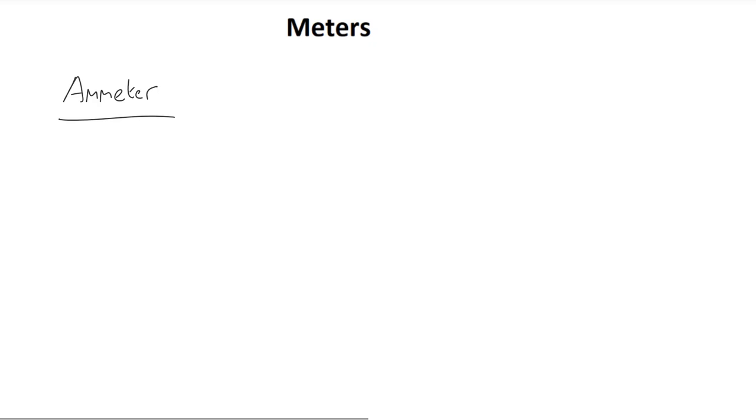If we wish to measure the current, two things have to be true. Firstly, the circuit must of course be on. If the circuit is not on, then there is no current flowing and therefore there is no current to measure. Secondly, the ammeter must be placed in series in the circuit. This is because if it was instead placed in parallel, then some of the electrons would flow through the ammeter, whereas other electrons would take the other possible path. Therefore, if we want to measure the current accurately, we must place the ammeter in series within the circuit.